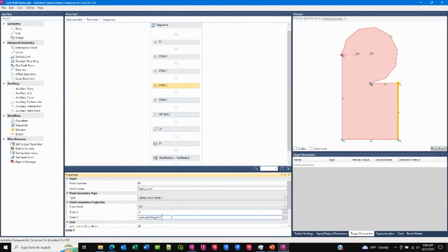Okay, so you see here I've taken the delta X from P4 to P3, 4 to 3, taking that delta X, and I just put a divided by 2 on it. By default, it looks like this. Okay, it's just a straight up curve. But I'm just making a change so I can show how that can propagate into Civil 3D and then update your whole drawing. Okay, so I want to save this file.